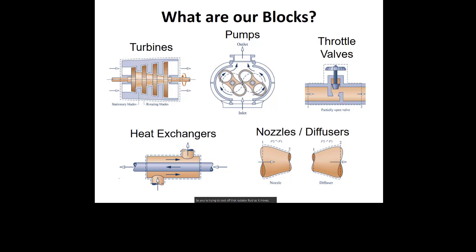And the way you do that is as your car moves, air moves over those fins. And even though you're not transferring mass, you're not pushing that radiator fluid out into the environment, it's all supposed to stay connected, right? But you're moving heat from the radiator fluid into the air as it moves over the fins.